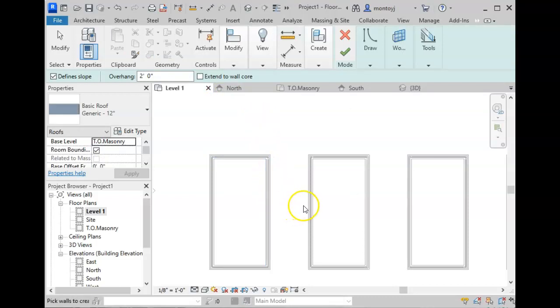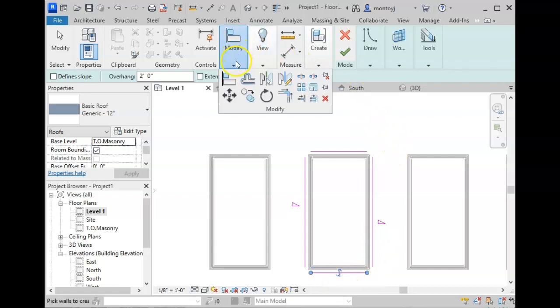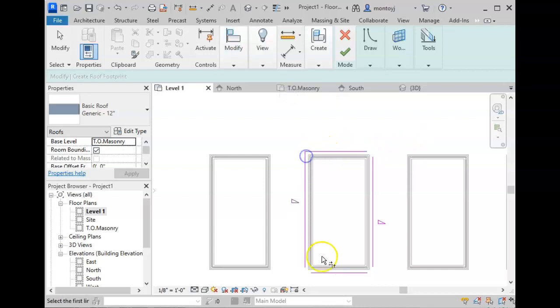The two long lengths get the slope. Then I come back here and I turn off the slope for these two that have no slope marker. I still have to perform my fix until I find the way to automatically do this. I have to override it by using my modify tool.